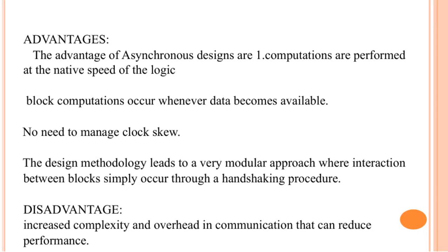Asynchronous designs offer several advantages that make them quite appealing. First, computations happen at the native speed of each logic block, meaning each part works as fast as it can without waiting for a global clock. This allows computations to occur whenever data is ready, enhancing efficiency. Another benefit is that there's no need to manage clock skew, which simplifies timing issues often encountered in synchronous systems. The design approach is also very modular, with blocks interacting through a handshaking protocol, which makes the system easier to scale and maintain.